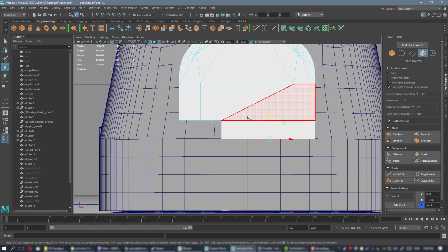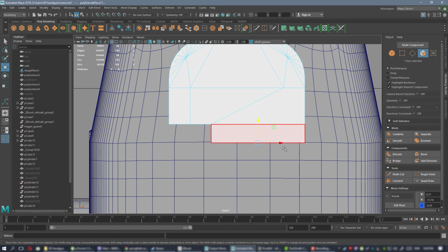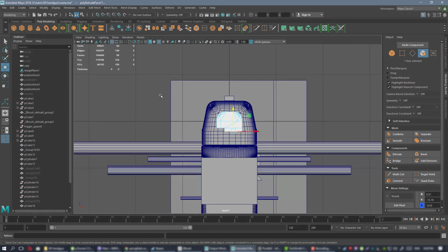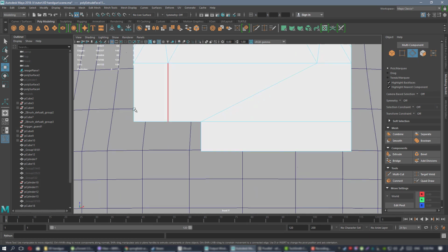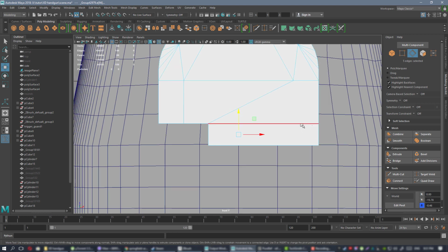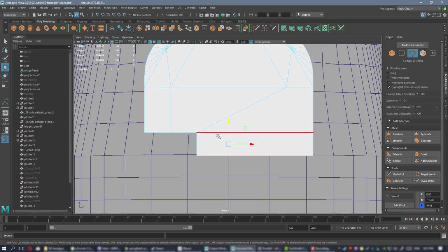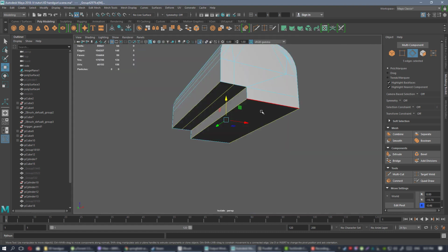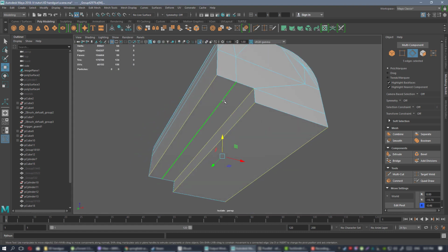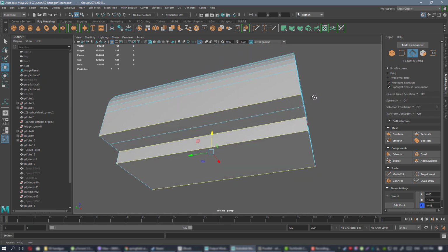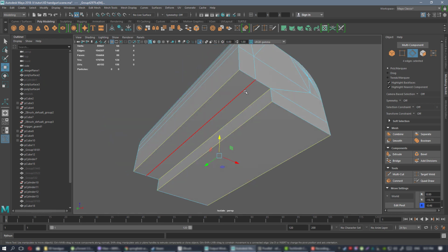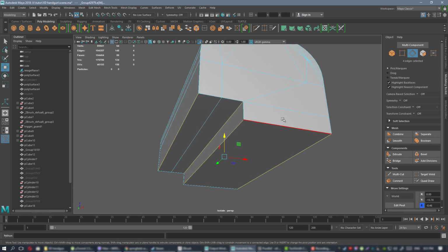And those corners should be beveled, so let's do beveling there. Deselect these guys, deselect these and these. You can see I'm just blind selecting those edges. That's because I just know how they're going to be selected, but sometimes you should be double checking it in a perspective view. You can see that I missed this one.